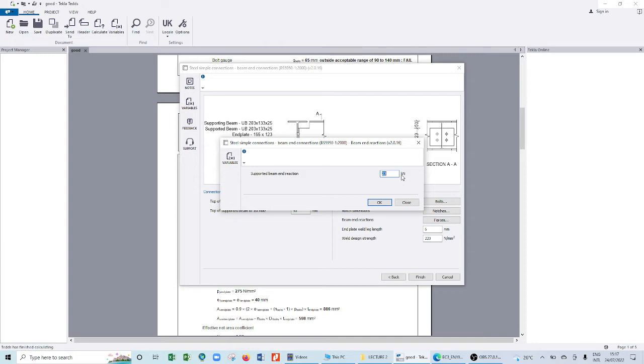Then for the slab, the load that we have got from Tekla Structures, you multiply by the slab area, because this load was given in kilonewton per meter square. So you multiply by the area that it is carrying. So meaning we have 14.4. I sum up my GK. Total GK will be 14.4 plus this. What do you get?